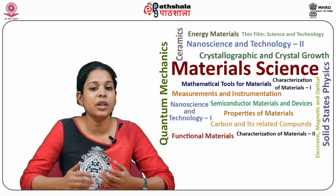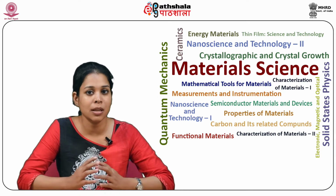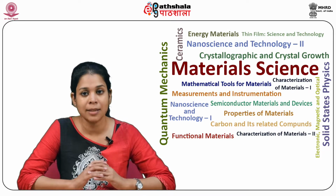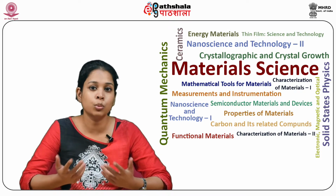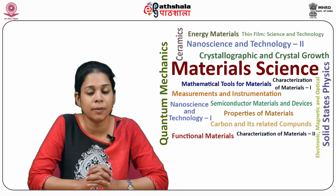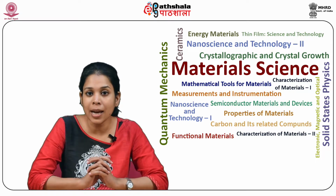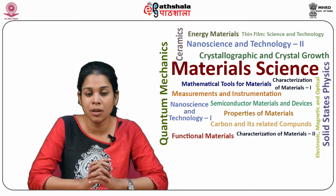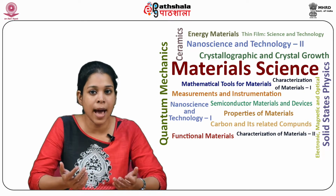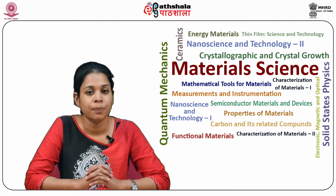Before moving to the conduction, let us discuss what electrical conductivity in ceramics is. The electrical conductivity in ceramics, as in most materials, is of two types. One is electronic and the other is ionic. Electronic conduction is the passage of free electrons through a material, and in ceramics the ionic bonds holding the atoms together do not allow for free electrons.